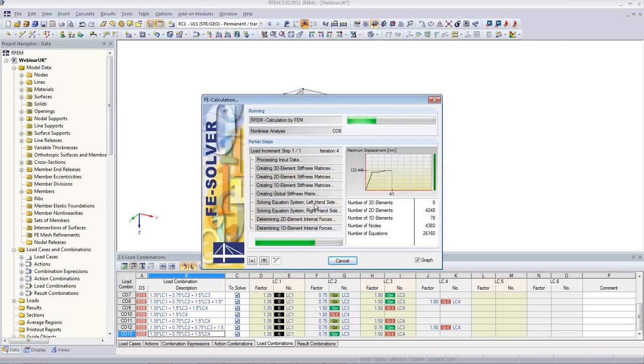The deflection or the drift or the skew that happens in the first iterations will have an effect in such way that there will be additional moments, and it has to come to a stop, so it has to find an equilibrium. And if for example the structure has not good supports or is not strong enough, there will be an instability, and you have to increase columns, beams, cross sections in order to get a stable structure.